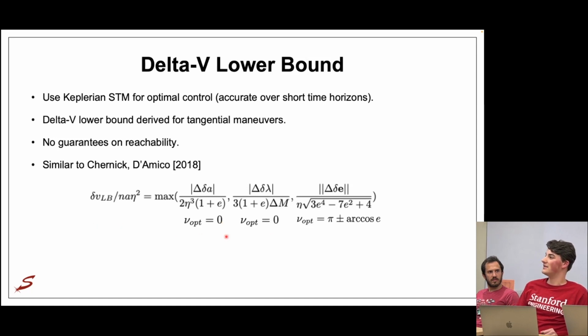But I would not say it's sufficient just to plug this into a reduced order model and expect it to output the true delta V. For example, if you were to do a change in relative eccentricity, you can almost never fire in the optimal direction. You have to align your maneuver with the desired phase of that change, and that's pretty much never going to be at this exact value, depending on what your maneuver is. So that poses the first challenge here.